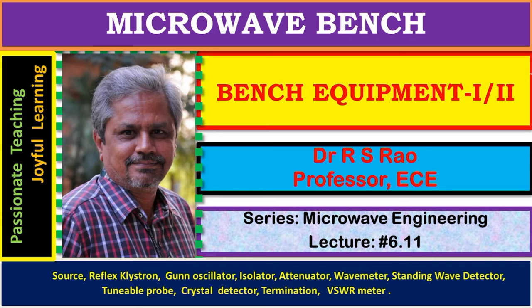In between source and termination, several components exist over the waveguide run. Immediately after the source, an isolator is placed. After the isolator, a flap attenuator, then a wave meter, which is followed by a standing wave detector, and then most of the times the termination, ending the bench setup. The standing wave detector is a multi-part or multi-component arrangement. In it there exists a tunable probe, a slotted waveguide section, a scale, and a rack and pinion arrangement.